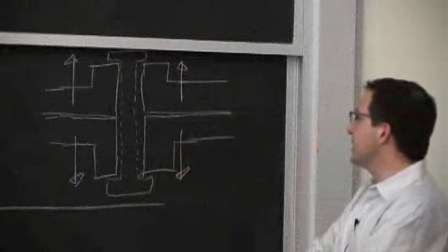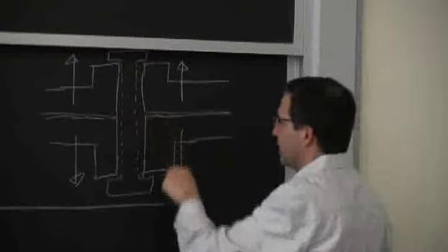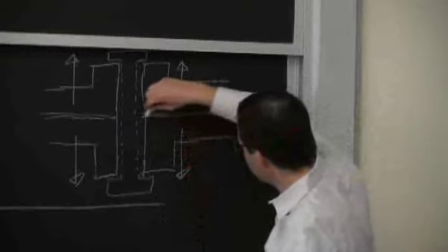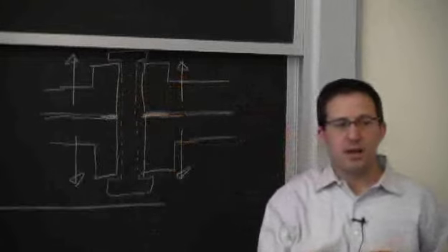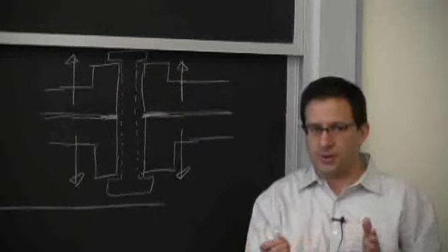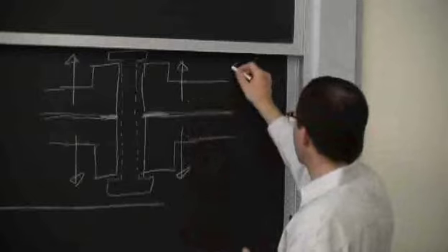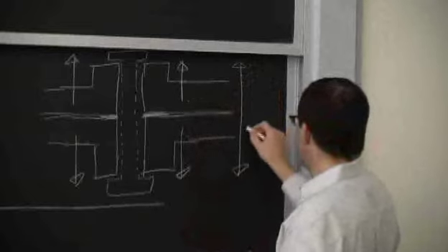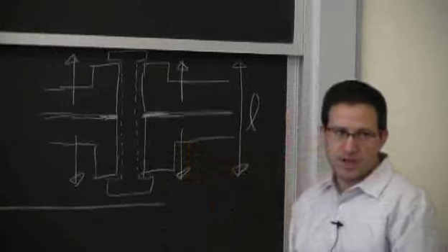What happens is if you have contact right here and you have contact right here and you keep it, it's a solid block that's exposed to your load variation in service. And because it's solid, we're going to talk here about L as being the total distance between the exterior of the flange on each side.